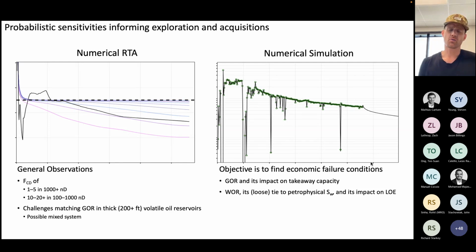Sometimes we'll have a water saturation of 40%, but the producing water oil ratio will be 6 or 7 to 1. Other times we'll have a water saturation of 70%, but it's a 1-to-1 water to oil ratio. We're currently talking with our petrophysicist and some other geologic people to assess why that's happening. And one of the primary drivers we believe is maturity, and what is registering as oil rich might not actually be mobile oil that's able to move through the system.